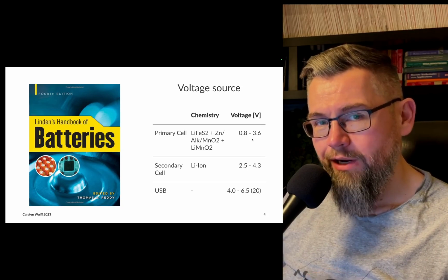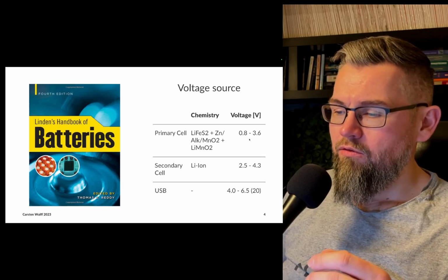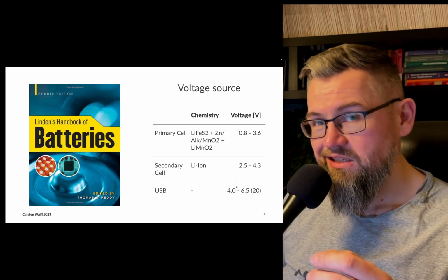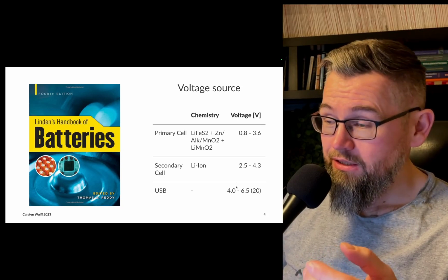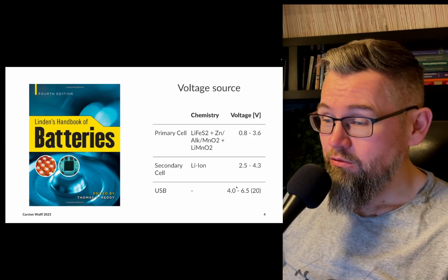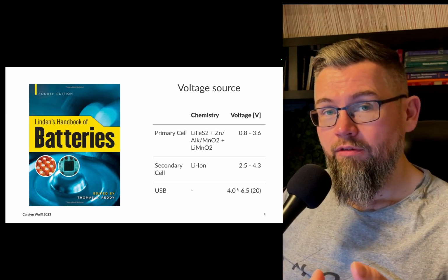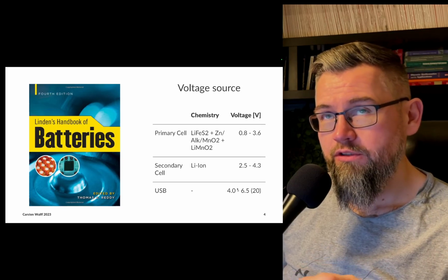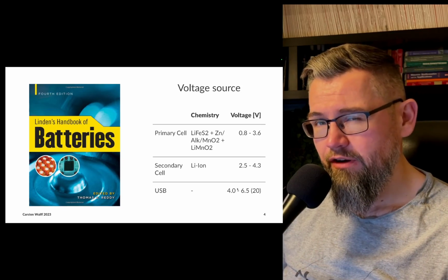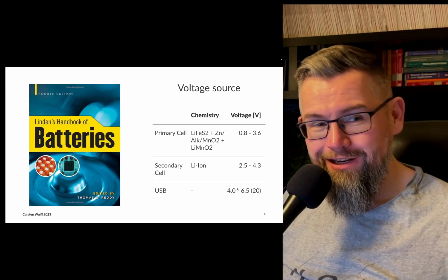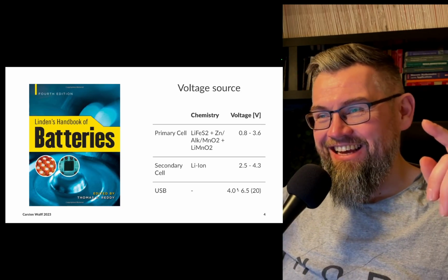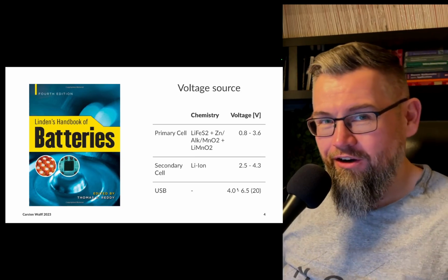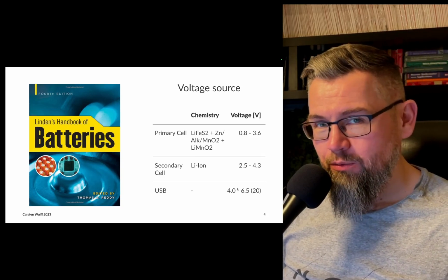use that voltage directly. And as we all know, we like to plug things into USB, whether it's USB-C or USB-A or USB micro or whatever they're called. And that voltage is usually between 4.0 volts and maybe up to 5.5. And then if you have a really long USB cable and you plug it in, the inductance can get you quite high spikes, maybe up to 20 volts.